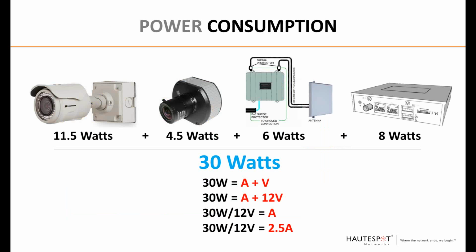So once we find that winter low of the peak solar hours, we need to add up the power draw ratings for every device that we're going to power on the solar job. We want to make sure to use the maximum watt rating for each product, so read those data sheets carefully. Note that some products have a different power draw rating for their PoE power versus auxiliary power.